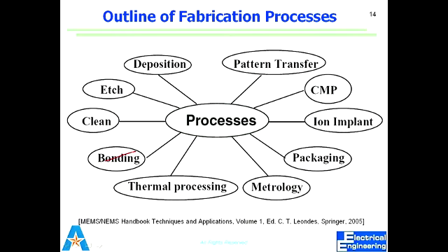Once we do that, we may be doing implantation, putting those, what you call, dopants. We might be doing etching to remove material from certain places. We may be doing deposition, putting material everywhere, and then maybe doing another lithography to define the pattern.